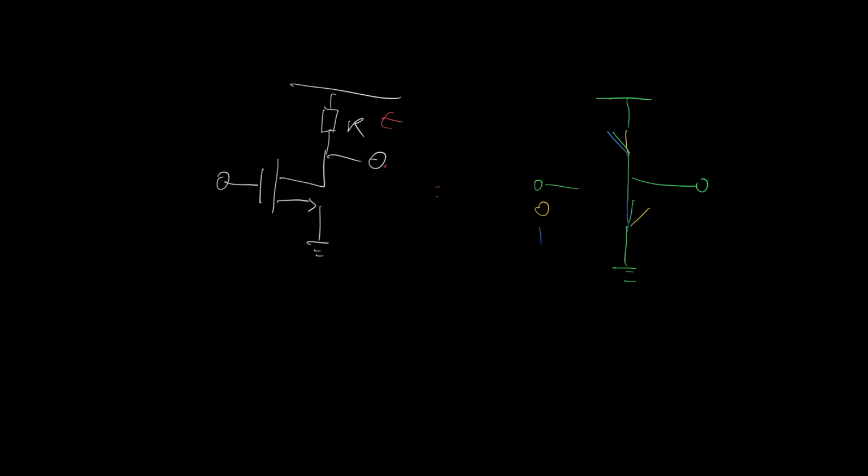Specifically, if we make some room here, we want to replace this pull-up resistor by a voltage-controlled resistor, and we know that FETs are voltage-controlled resistors, so I want to put a FET in here, and we'll explain presently why we want it to be a P-channel FET, and it's going to depend on the input voltage here. And don't worry about the sizes of the FETs being horribly different. They're supposedly identical FETs, just P-channel at the top, N-channel at the bottom, and we have ourselves an actual inverter. The input A, the output B.